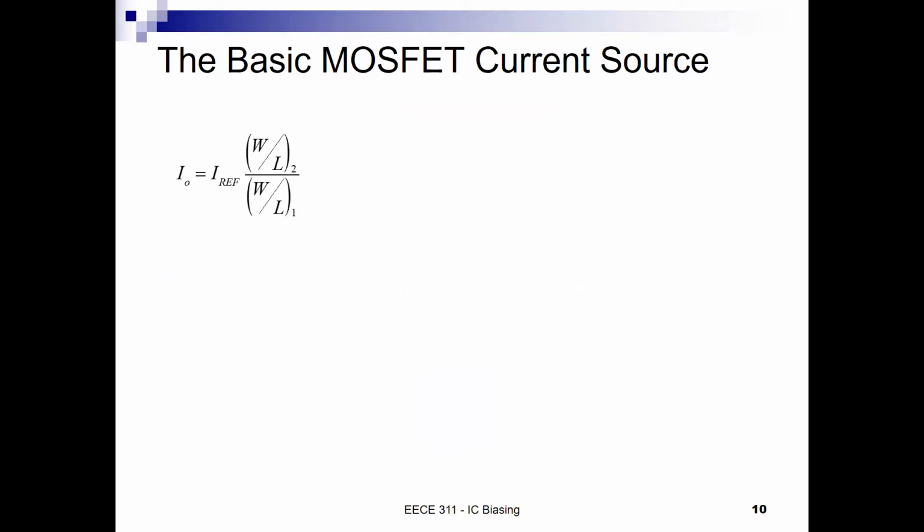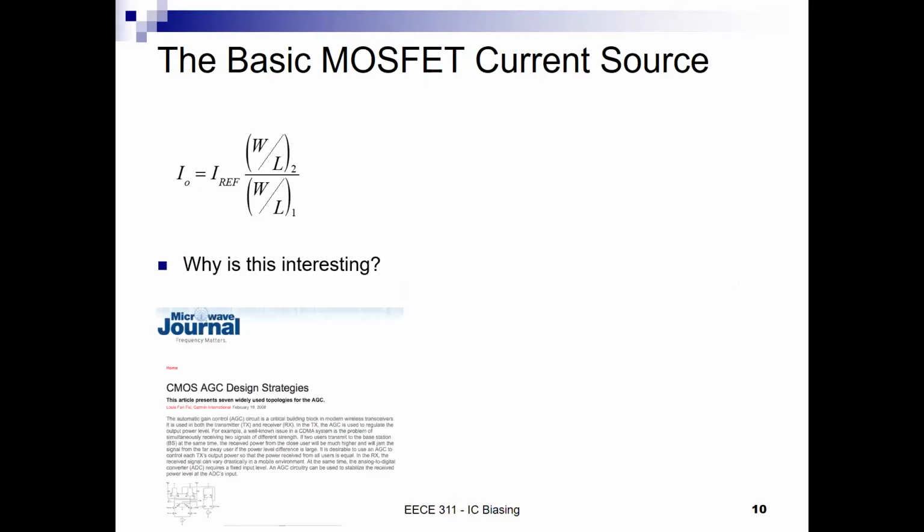And on the next slide, we say that this is interesting. Now I can adjust the weight of the reference current. Not because we like things to be complex, but because it is really used on chips everywhere. The basic concept is that we can have one I reference branch on the chip, which is expensive to implement.